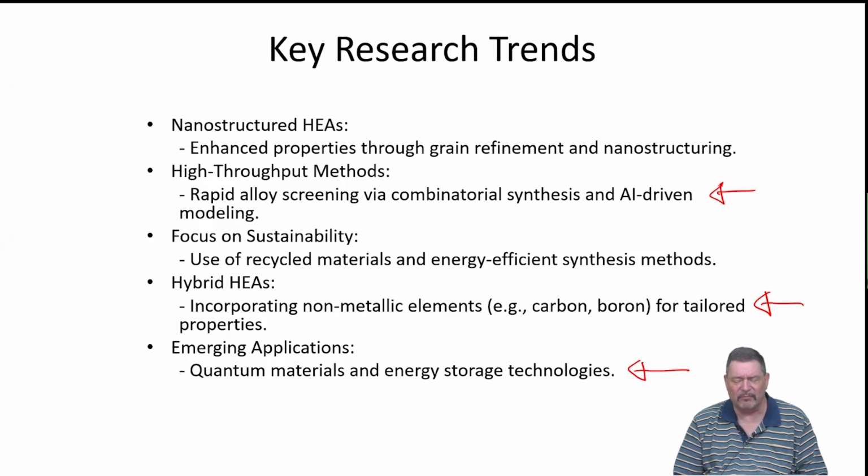And so I would say, it's okay to get a first shot at what the properties should be, but you have to go through a second step and do proper characterization of the material in shape, quantity, and processing conditions as close to, or much more close to, the conditions you are using in your application itself.